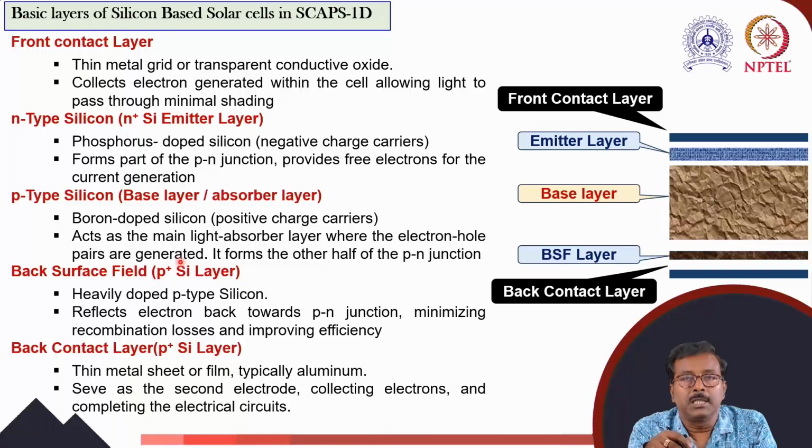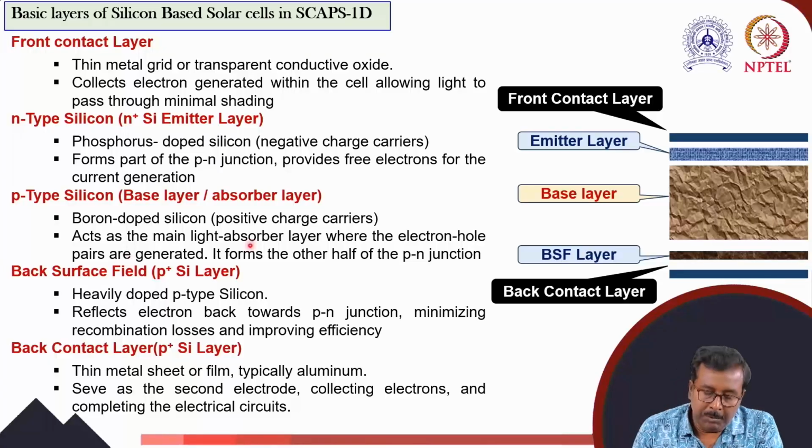In most of the cases, highly doped silicon, say p-doped silicon, below the silicon base or buffer, acts as a back surface field. Because we discussed this back surface field, due to presence of band offset and the charge associated with these things, it acts as reflecting the desired carriers and passing out the other things.